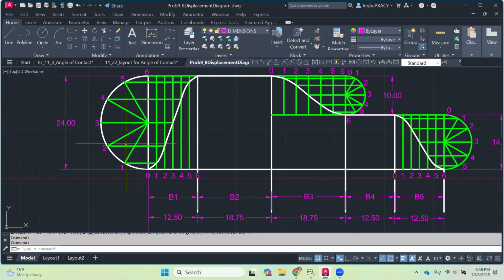Okay. So because it's 180 degrees, 6 into 180, or 180 divided by 6, is 30 degrees. So 30, 60, 90, 120, 150, and 180. Now, as we go around clockwise, my 0 starts at the bottom, and then I have my 1, 2, 3, 4, 5, 6. So notice 6 divisions horizontally, 6 divisions around that radius.